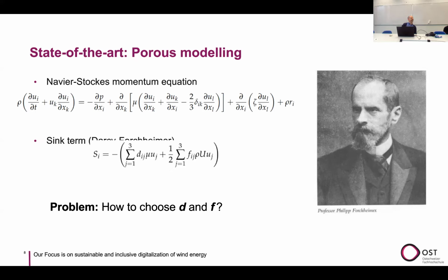I added him because he is actually an alumnus of ETH, so I thought it's quite interesting. Basically what this does is it just adds more resistance. So the perforated screen would be providing resistance, and there are two terms here. One is proportional to the speed and viscosity of a fluid, and the other one is proportional to the square velocity of a fluid. Usually the first one is called the viscous term, and the second one is the momentum or inertial term.